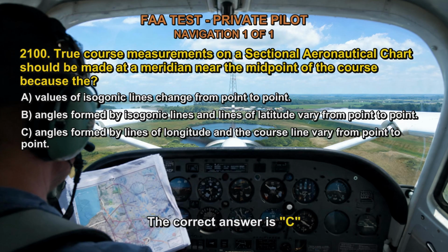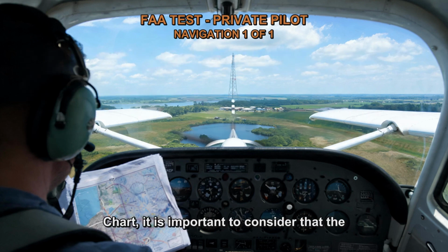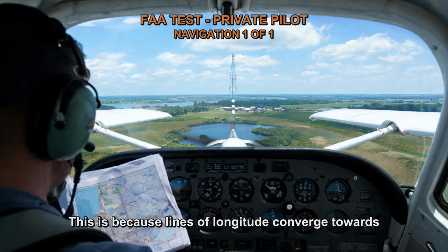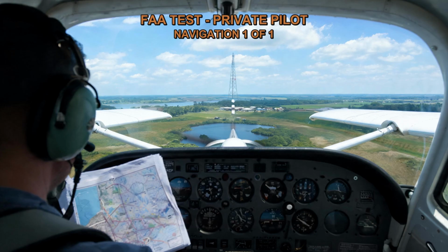The correct answer is C. When measuring true course on a sectional aeronautical chart, it is important to consider that the angles formed by lines of longitude and the course line will vary from point to point. This is because lines of longitude converge towards the poles, resulting in a distortion of angles as you move away from the meridian near the midpoint of the course.